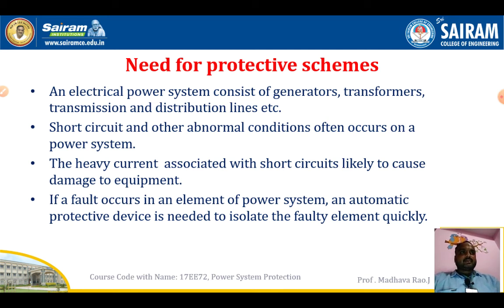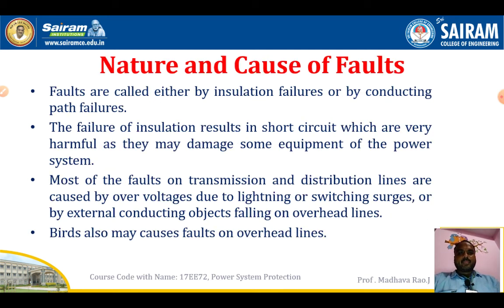Next, we will see the nature and causes of faults. Why do faults occur? Faults are caused either by insulation failure or by conducting path failure.